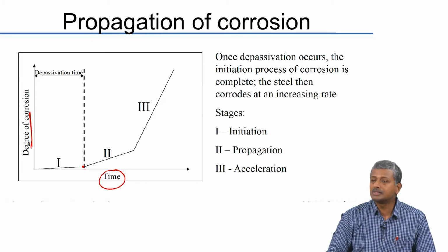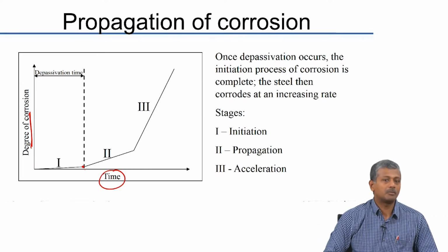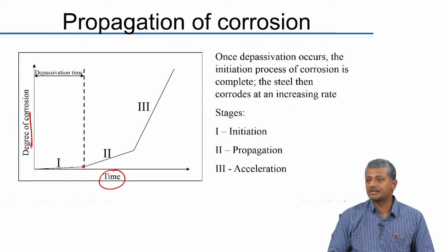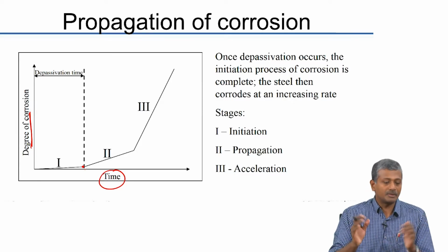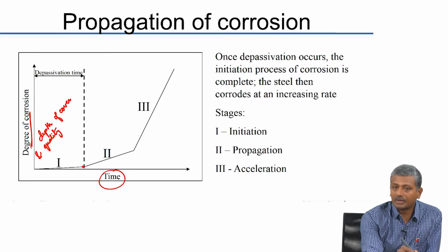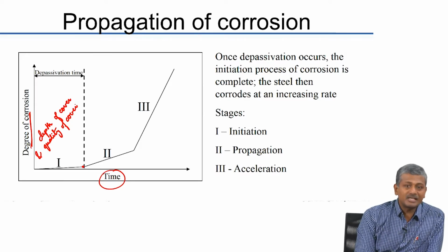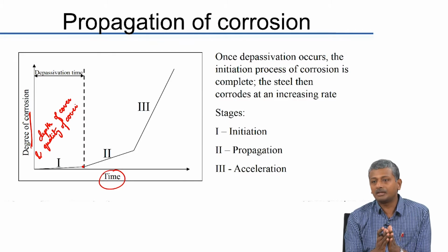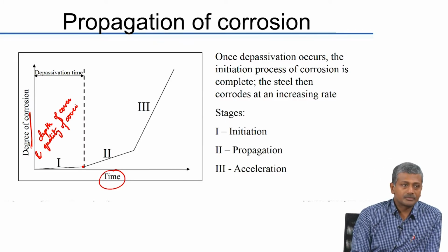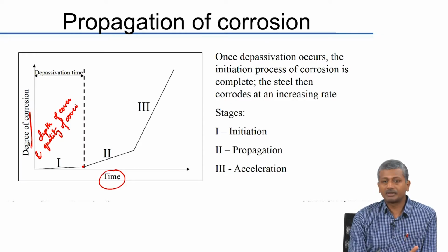So, that is determined by what? Diffusion is a phenomenon leading to the penetration of chloride or carbon dioxide. But what is the primary factor that is governing that? The cover concrete, right? The depth of the cover and the quality of the cover, quality in terms of permeability of the cover. So, the cover being deep or the cover being less permeable would tend to increase the time it takes for depassivation to happen. So, a lot of protection strategies against corrosion are obviously based on improving the concrete cover characteristics.